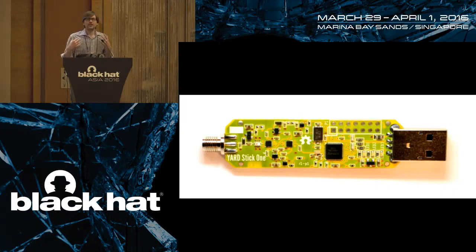I can't even give you a comprehensive list because it's so long. This particular part is designed for sub 1 gigahertz radio frequencies, so up to about 960 megahertz, I think it goes. And it covers some very popular bands like 300 megahertz band, 400 megahertz band, 900 megahertz band, 868 megahertz. All of these popular frequencies below 1 gigahertz for low-cost equipment operating in unlicensed bands.